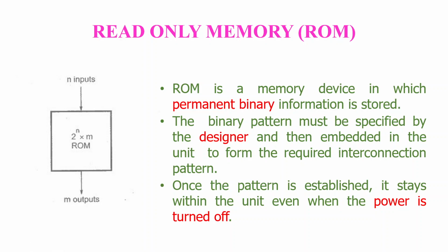In the previous video lecture I explained the internal memory structure, which consists of rows and columns. Rows are specified by address inputs, that is, a location, and the m data outputs are represented by columns. For example, here we are reading a word, that is a byte. Byte means 8 bits, so m equals 8. In this row we will have 8 ones or 8 zeros, a group of 8 bits, that is, 8 columns will be there, for example if m equals 8.